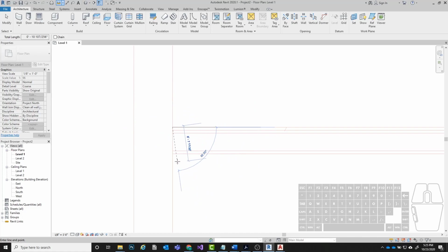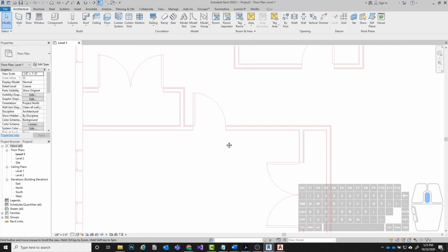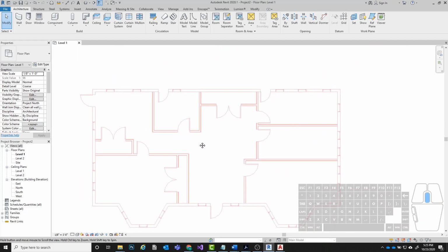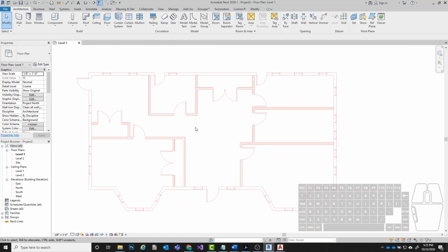If I drag this down here and measure the thickness of this interior wall, you can see that this one is 5.5 inches, okay? Those should be the only 2 wall types we have inside of this project. So we know our exterior walls, we're going to have to draw all of those at 8 inches, and our interior walls are all going to be 5.5 inches.